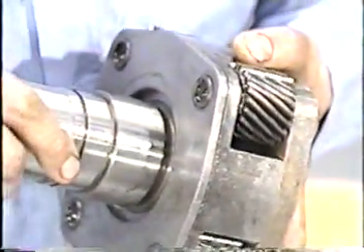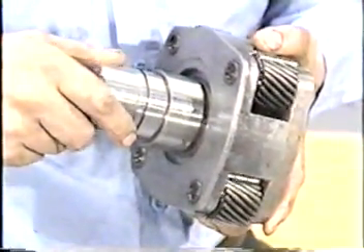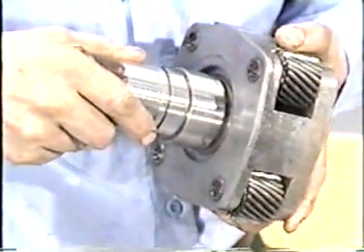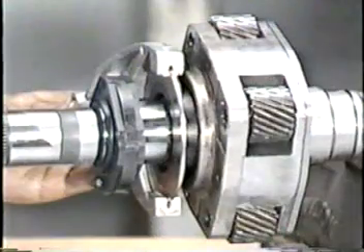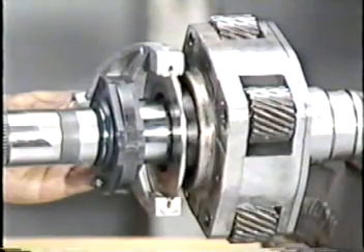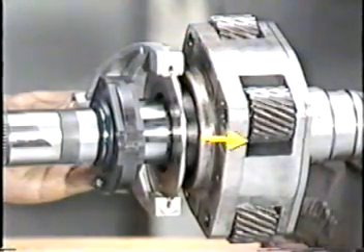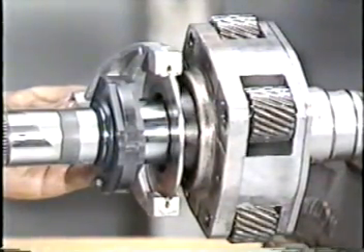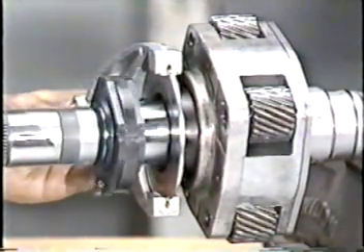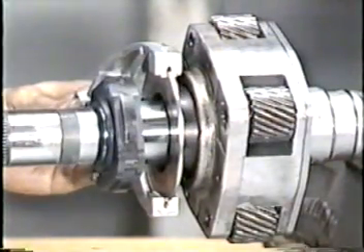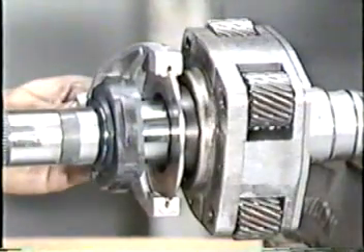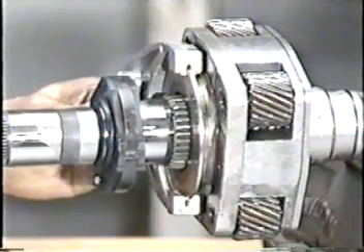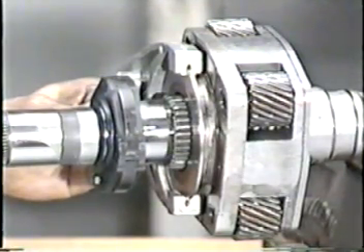The second function of the transfer case, gear reduction, is accomplished using a planetary gear assembly driven by the input shaft. When the transfer case is in neutral, the sun gear, planetary gears, and annulus gear all turn freely with the input shaft. In this condition, no power is transmitted to the output shaft. In two-wheel drive and also four-wheel drive high, the reduction hub, controlled by the high-low shift fork, splines the input and output shafts together in direct drive.